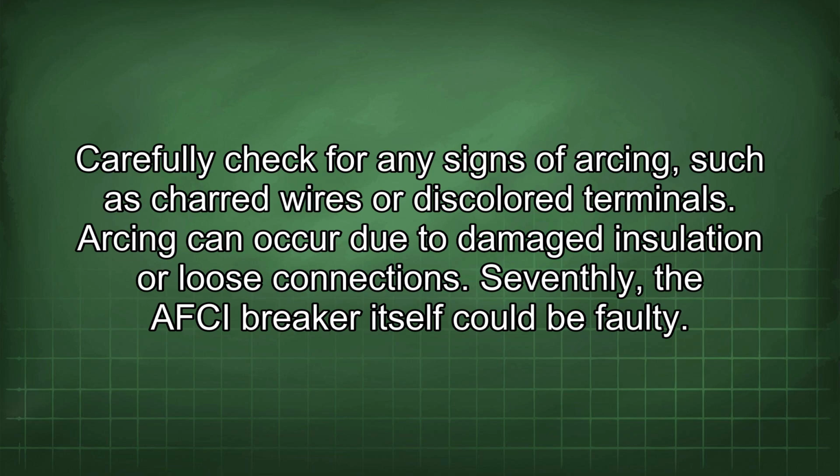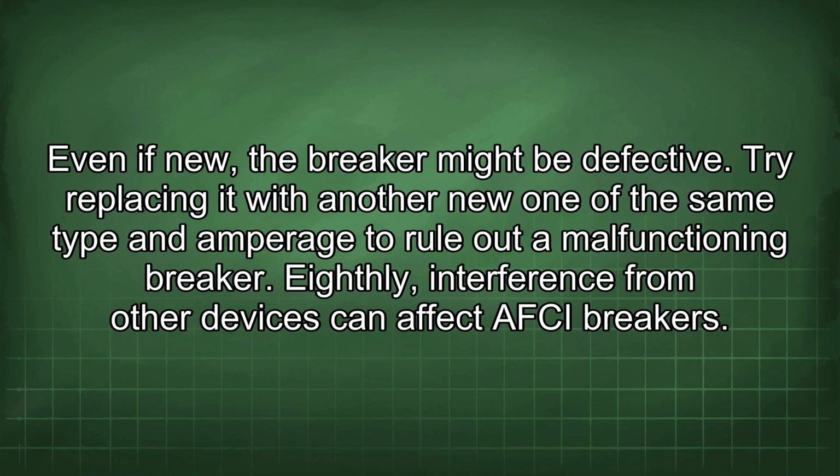Seventhly, the AFCI breaker itself could be faulty. Even if new, the breaker might be defective. Try replacing it with another new one of the same type and amperage to rule out a malfunctioning breaker.